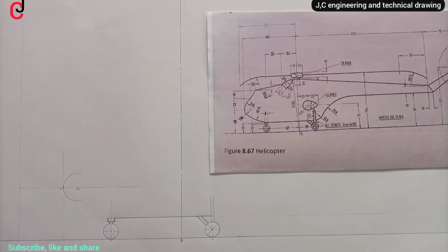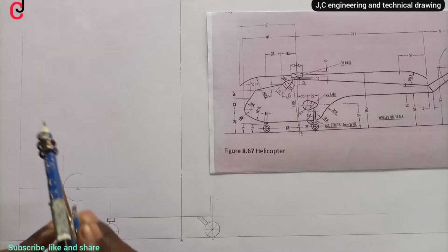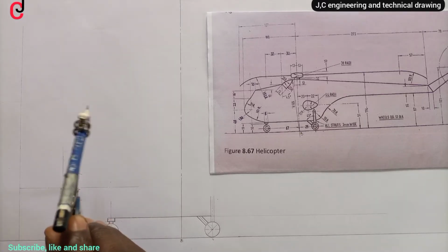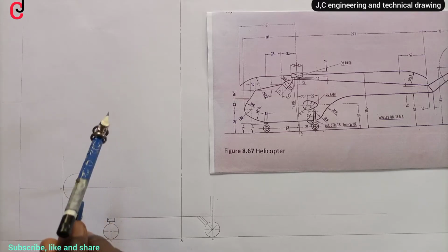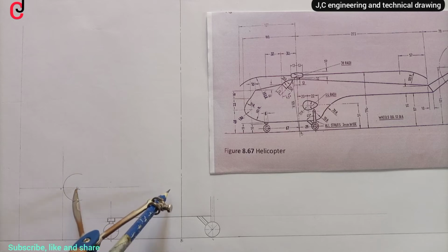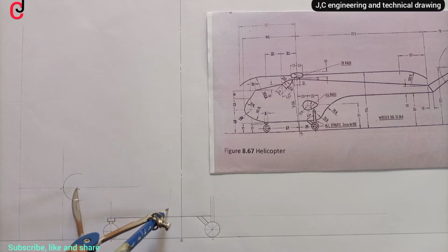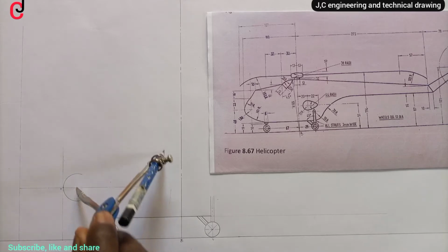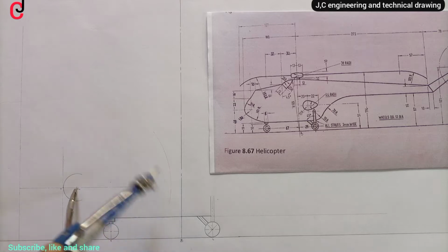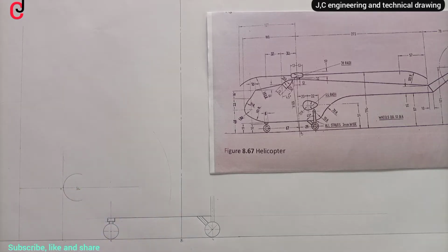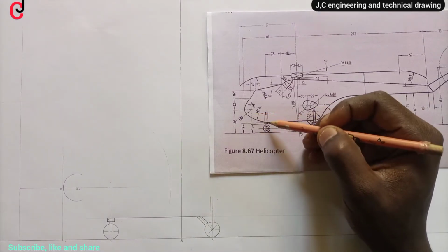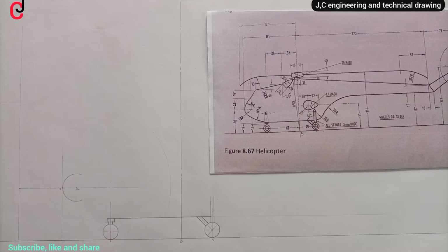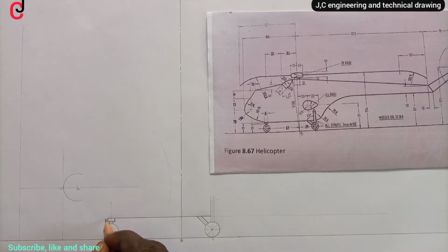Now using point O2, we'll place a compass pin at point O2. Our compass is already open to 88 millimeters radius. Then we'll scribe an arc. Now from our diagram, you can see that this arc here is touching the tip of this portion here. So we'll call this point O3,